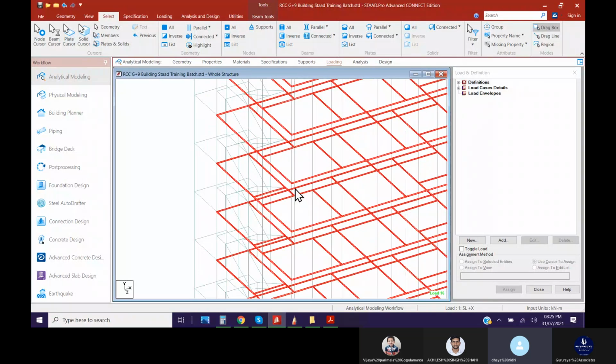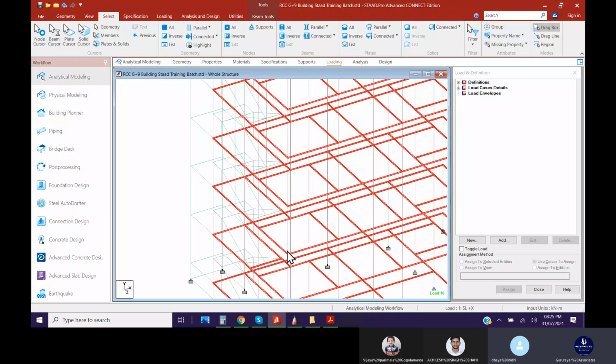Because you've got three varieties. Anything we can use, sir, handmade or machine press. Same, as long as you get that compressive strength, that's it. As long as you are getting the compressive strength of the brick, normally the compressive strength is sometimes 5 Newton per millimeter squared or 6. It differs. So until we get it, it's okay.